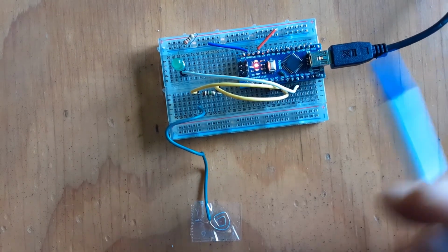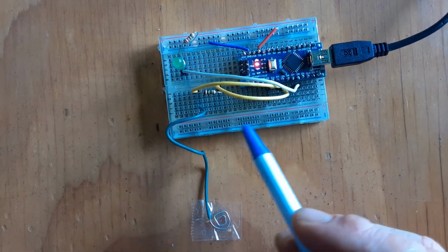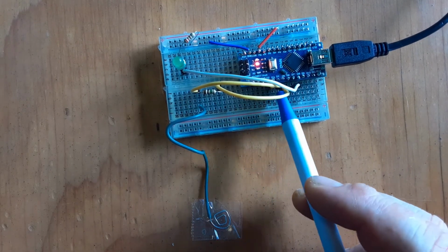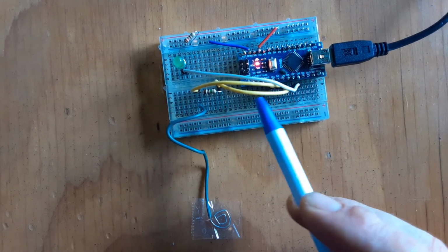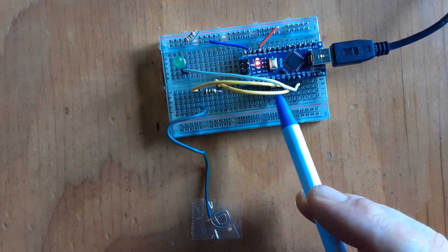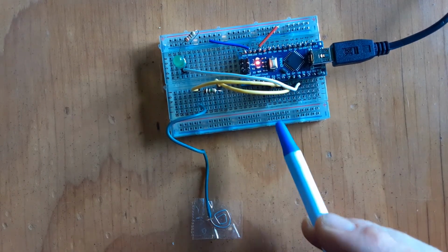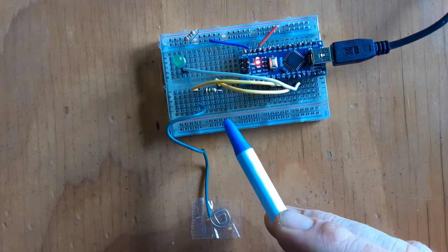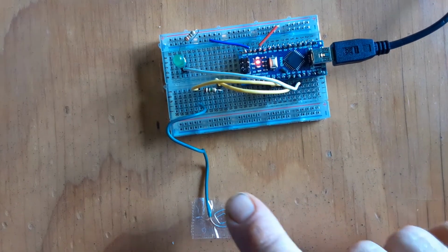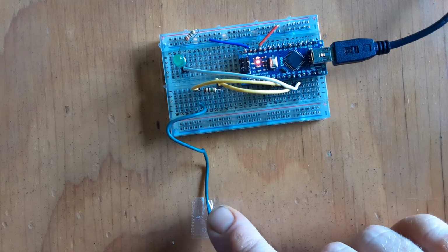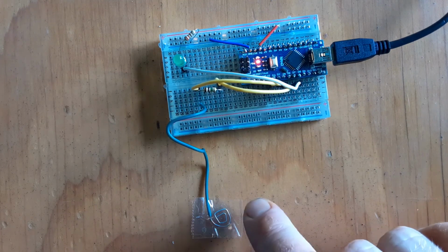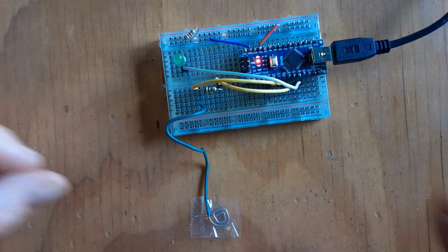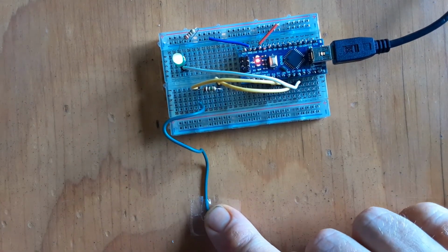Now that the code's finished and uploaded onto the microcontroller, just like the setup we talked about earlier, these pins are connected across a resistor, and the microcontroller detects the difference between them. When my finger comes in and gets really, really close to that wire, we get a capacitor, so then it becomes an RC filter instead of just a resistor, so there's a lot more change.